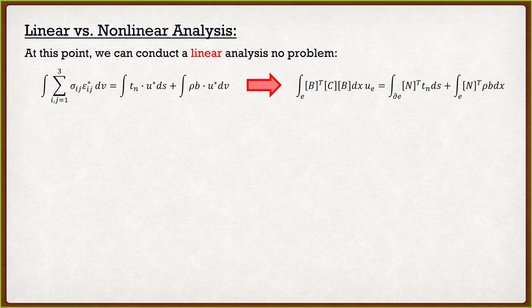It's nice and easy. Now, if we look at this equation, this was our stiffness matrix. That was no problem. And this was the two components of our nodal forces. Again, this component right here doesn't have our applied concentrated loads at the nodes, but those are also easy to tack on. So we basically have our stiffness multiplied by a displacement vector is equal to a force vector. And that's exactly what we did back there. We figured out what our stiffness was, we figured out what our nodal forces were, and then we solved for our nodal displacements. And this is why you guys are thinking, Clayton, baby analysis. I can do this in my sleep, no problem at all.